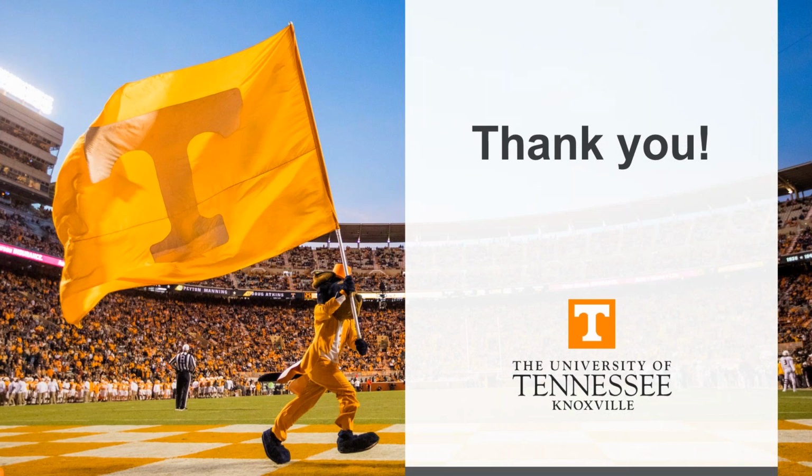We had one last question come in at the last minute. For the T-Stub flange connection, did you limit the plastic strain to 5%? Yes, that's the default, and that's what we were showing. I have, perhaps not in the T-Stub, but in other verifications, varied that plastic strain limit, because I think it does show some interesting results as you vary it.